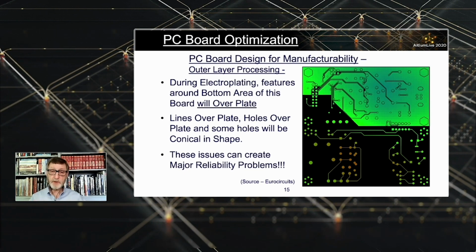Unless you want your circuit boards to be warped and twisted and look like a potato chip, you need copper evenly distributed all over the inner surfaces. You should be adding copper pour to every surface of your boards. And if you want to know how to attach them properly, attend one of Lee Ritchie's classes on power delivery, or attend one of mine on power delivery, and we'll tell you how to properly attach that copper so that it does its job as it's supposed to.